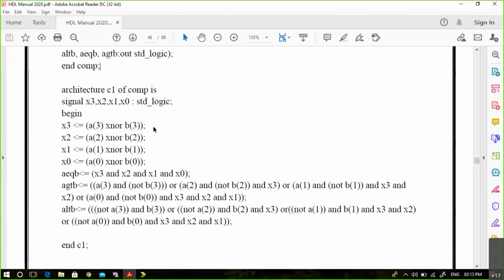Now whenever we compare 2 binary numbers, always we have to first check with the MSB. When we first check with the MSB, we will come to know whether the MSBs are equal or greater or lesser. In the MSB itself, if we take a decision, let us say A is having 1, B is having 0 there, immediately we can come to a conclusion, A is greater than B. So that is how we have to start with the MSB itself.